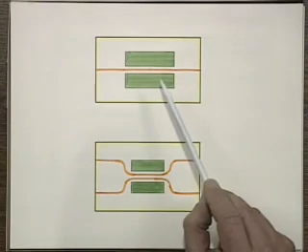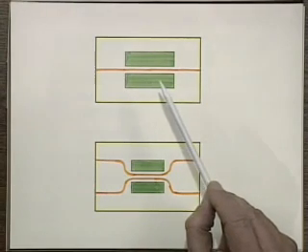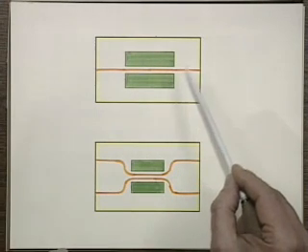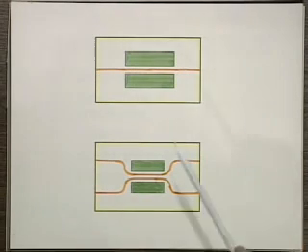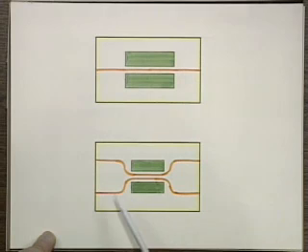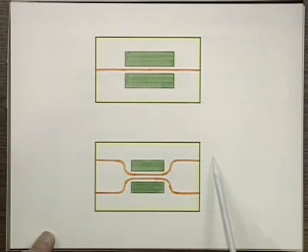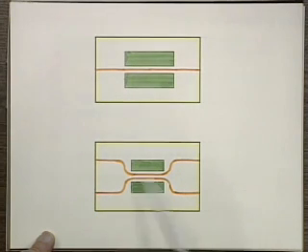Now, if you want to use it as a coupler or as an intensity modulator and so on, you have to combine several waveguides, two waveguides together, and then you can create a coupler. Here I've chosen this example where I have one guide that looks like this and then the other that looks like that. If I put light in one arm, normally it would come out over here, but depending on the closeness of these two cores, some light will be coupled into the other side and come out over here. So this is, let's say, a fixed coupler.